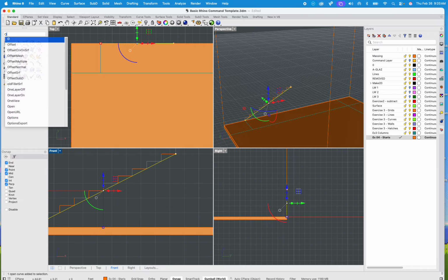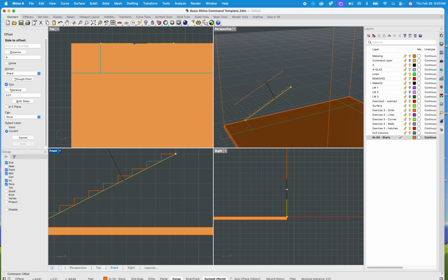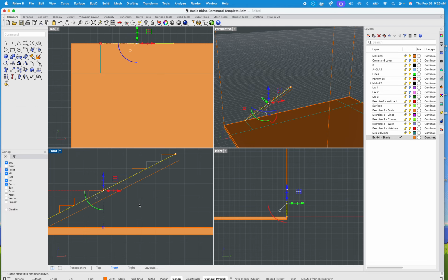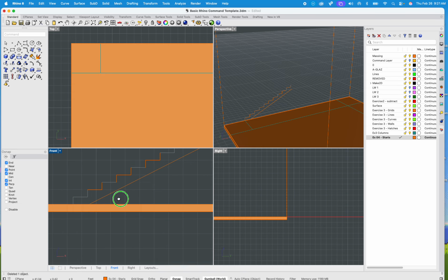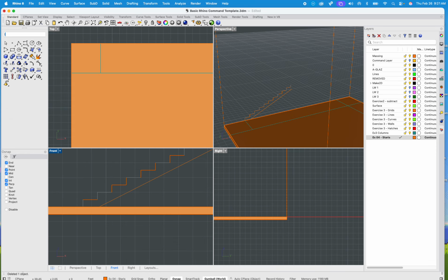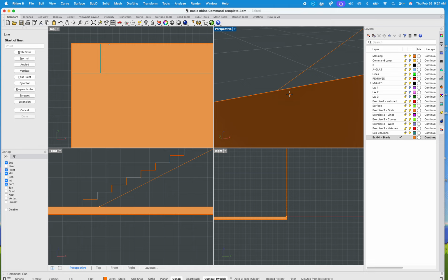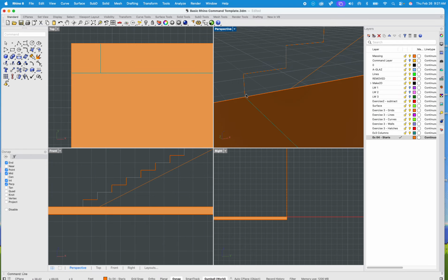But offsetting, typically we do about 6 inches worth of concrete. So I'm going to say 6 inches, go down. Don't actually need that other piece, but hopefully you're starting to see kind of a stair, right? You're starting to not only see the top of the stair, but of course the bottom of the stair too. And again, if this is absolutely confusing, don't worry guys. We'll hit you hard with stairs and ramps and rails also in D1 or definitely G2, especially with Professor Bosoff.